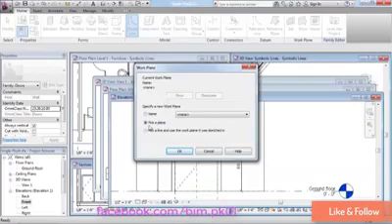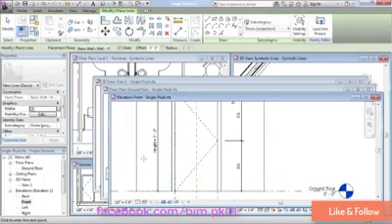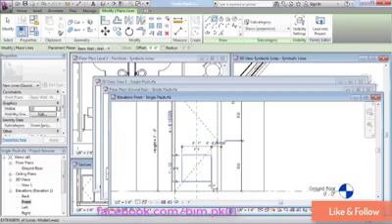Now, in both cases, whether you're drawing a model line or symbolic line, Revit will want to know what plane you're drawing these lines on. So I'm going to pick a plane here, click OK, and draw these lines relative to just the surface of the wall there. Go over here and choose rectangle. I'm going to do this a little sloppy for this example, just eyeball a rough shape, and I'm not going to set it up parametrically or dimension it. You can do that as an exercise if you like. I'm just simply going to get the general idea across here.